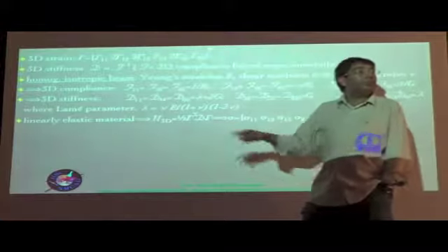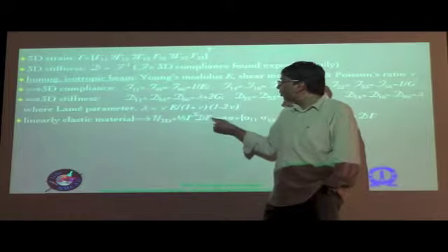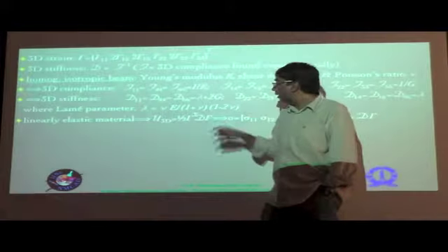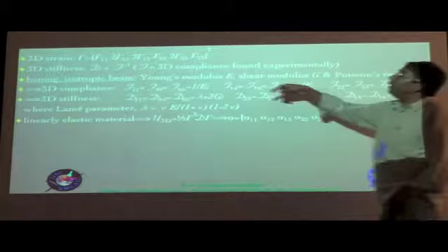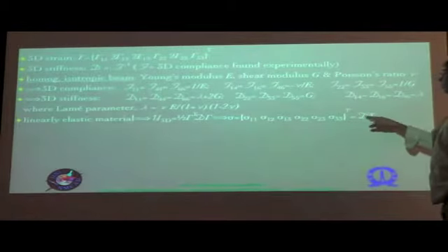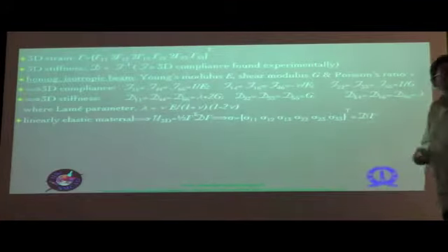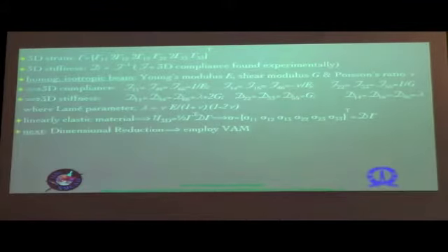So for a linearly elastic material, the U3D, the energy per unit volume of the material making up the beam, is given by 1/2 gamma transpose D gamma. In other words, it's quadratic in the gammas, and the corresponding stress, work conjugate to the Cauchy strain tensor that you have here, is this particular thing. Again, the ordering is the same as what you have there in terms of the components. And then, of course, it's a linearly elastic material, so it's proportional to gamma.